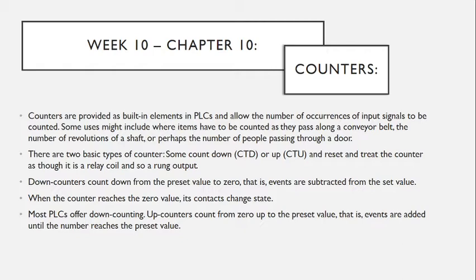We have these two types, and reset becomes very important for using the counters. And you are going to see how we can use the done bit, in a very similar way to how we were using it for timers, to turn on or turn off any output. Now I'm going to look at it.